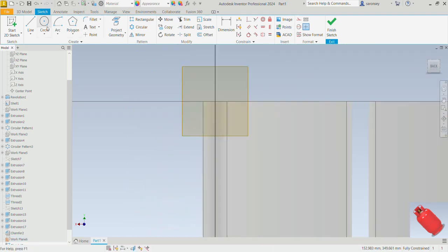We are going to pick the circle command. Let's draw a circle here. We can even pick the arc, the 3-point arc. We'll place at this point and that point and specify the radius of that as 4 and enter. We can right click and then OK.